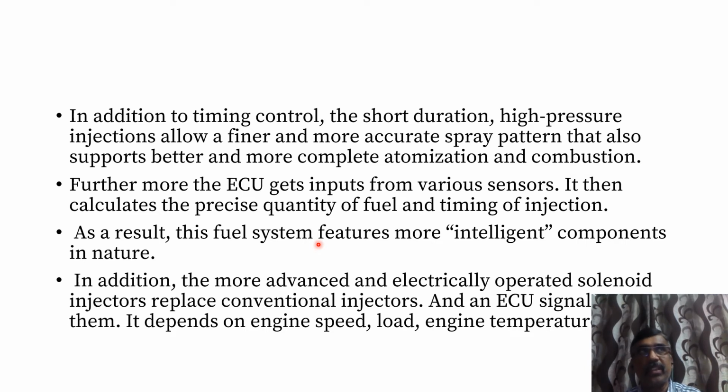Likewise the oxygen sensors and other sensors sense the amount of fuel required, and that will be regulated by this ECU. As a result, this fuel system is more intelligent in nature. In addition, more advanced, electrically operated solenoid injectors replace the conventional injectors, and an ECU signals them. It depends upon the engine speed, load, engine temperature and other parameters required to control the fuel.